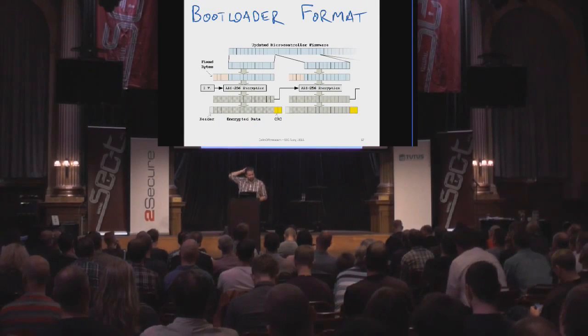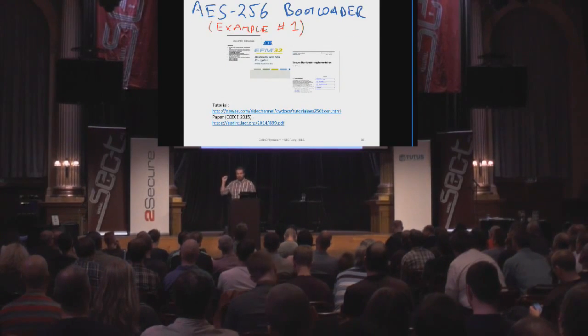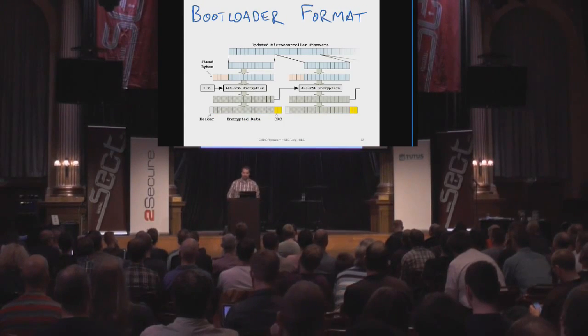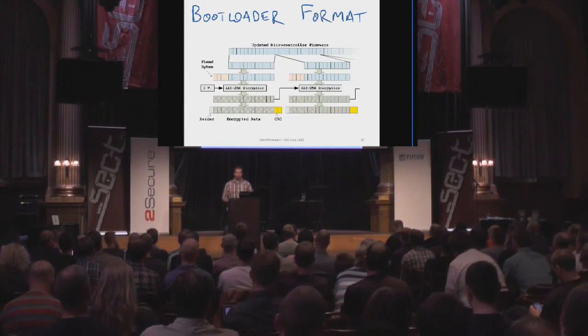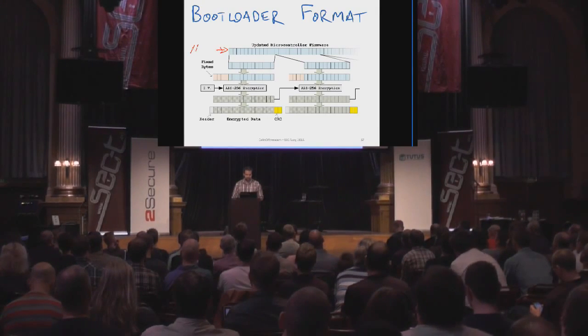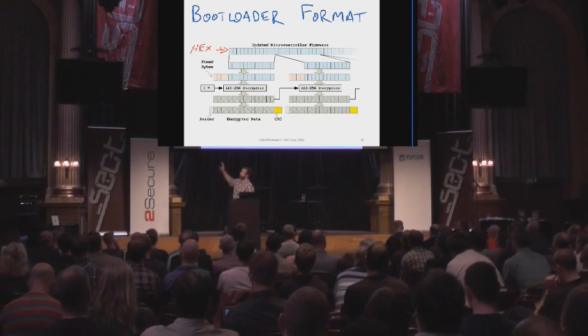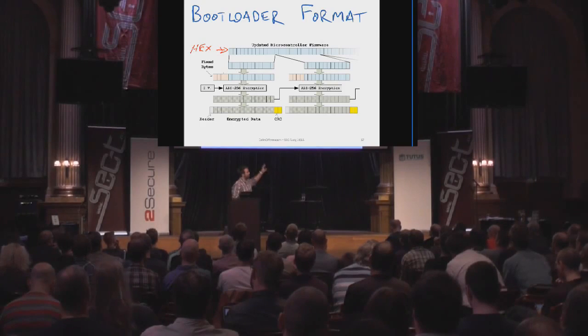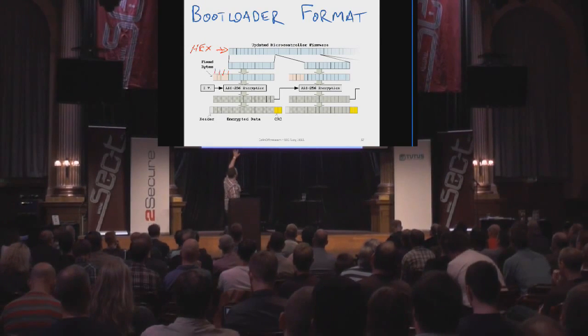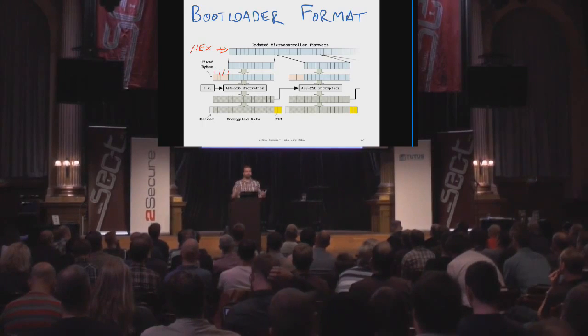In this case, the online published format, I've basically collected a bunch of app notes and rewritten a generic bootloader, but it uses all the same principles. Most of them are designed to run on small devices. You take the hex unencrypted file, or a binary, so that's the file they want to distribute. They chop it up into 12-byte lengths, and they just add 4 fixed bytes at the beginning, so this gives you your 16-byte block. The idea of these 4 fixed bytes is that they're going to be the signature.